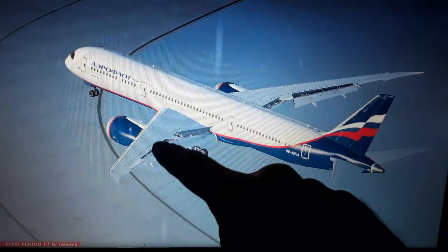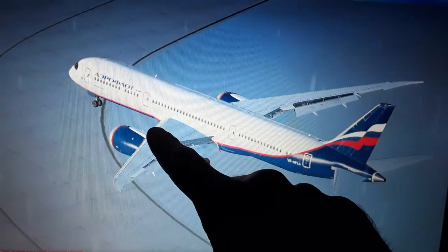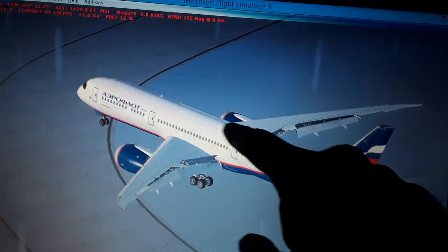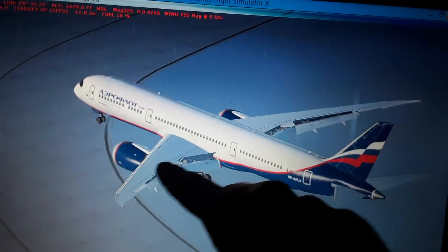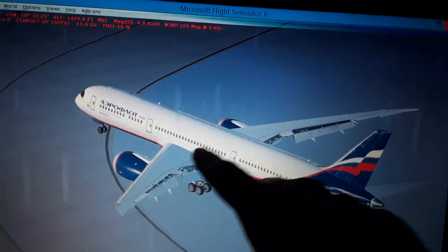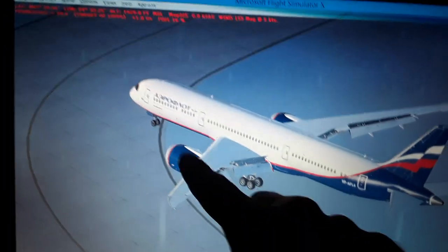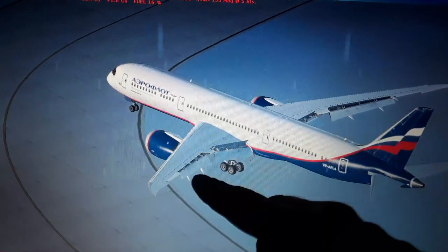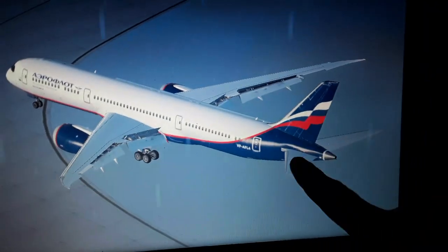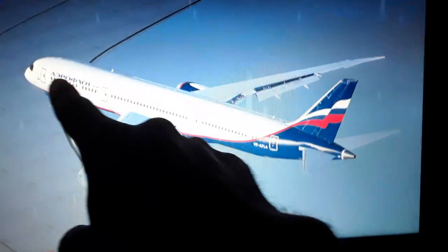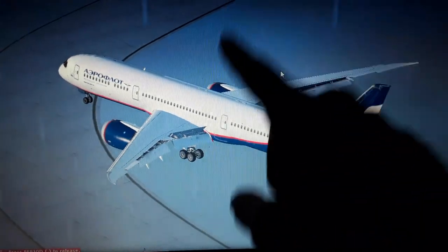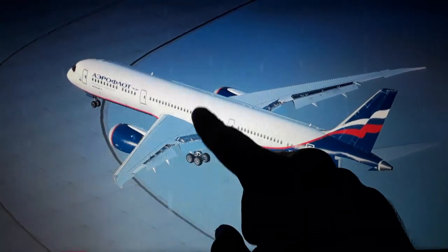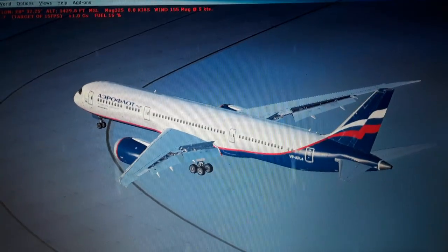The wing surface area holds the weight of the aircraft as it flies. We have the mean aerodynamic chord position, about 23% of the MAC, about here, where the maximum aerodynamic lift occurs in the top surface of the wings, and also the stall will begin. We have the thrust vectors from the engines. You can see the top surface of the wings and the bottom. I will show you the difference. The vertical tail also. So we have the longitudinal axis, the lateral axis, and the vertical axis that transverses approximately here where the mean aerodynamic chord position is, the center of gravity of the aircraft located.